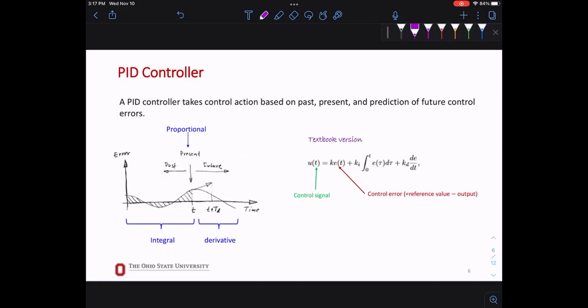So in designing a PID controller, the fewer of P, I and D we use, the better, because it's cheaper. If you see that with just P you can't get where you want to go, then you decide: should I go PI or should I go PD? You don't go PID right away, because then you have to tune three things. And imagine times six, if it was a six-joint robot, if you're afraid of the robot. Okay, all right.